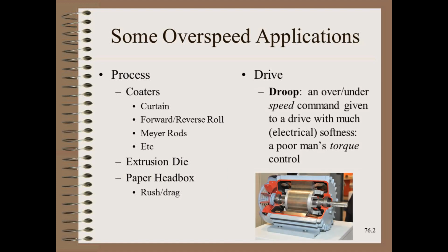We use droop and some drive control methods when running stiff webs. Here, the motor is nominally in draw or speed control, but the gain is very low. Thus, the speed difference command set by the operator is more of a suggestion. What really happens is that the drive is running in a hybrid of speed and torque control.